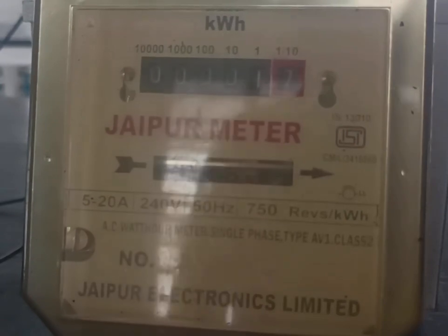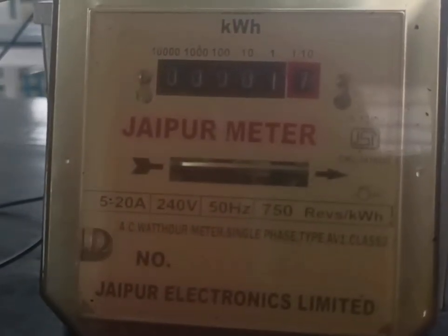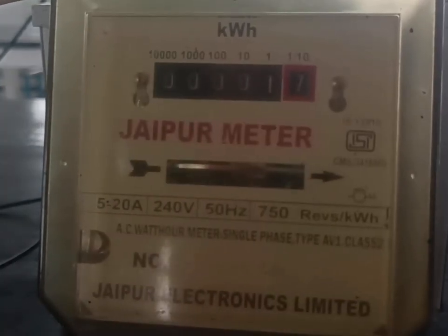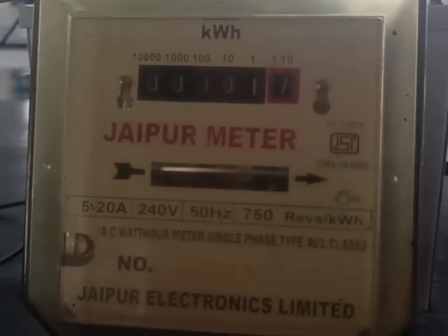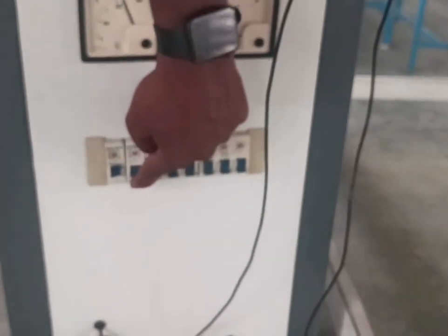Now we have to take the wattmeter, ammeter and voltmeter readings, and I also have to note the constant value for 1 minute. In that 1 minute, how many rotations the disc makes will be noted in our observations. Now I am going to switch on 1 more amp of load. In this condition again we have to take the reading in the same manner.